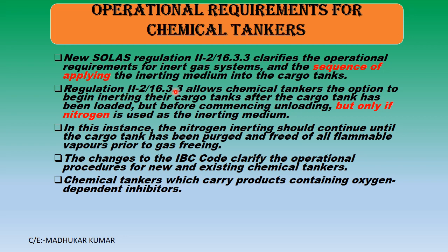Regulation 2 to 16.3.3 also allows the chemical tanker the option of inerting their cargo tanks after the cargo tank has been loaded. Okay, so after loading also the padding and all is being done, but before commencing unloading, but only if nitrogen is used as the inerting medium. So inerting medium also they are given as nitrogen. In this instance, the nitrogen inerting should continue until the cargo tank has been purged and freed of all flammable vapors prior to the gas freeing part.